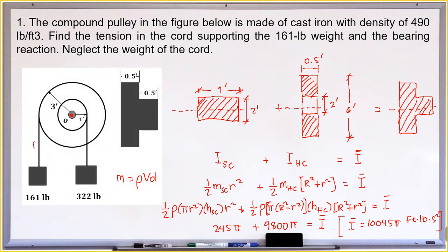The tension here is 161 point something, and this one is around 321 point something. If you notice, the tension here is small due to the downward acceleration. With the downward acceleration, it is as if the right side rope, the rope on the right, makes no effort.